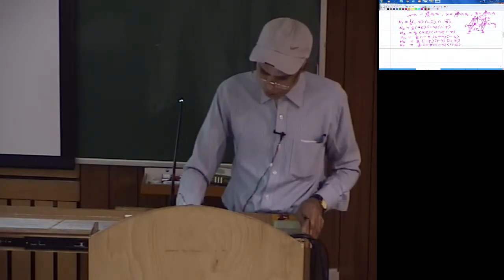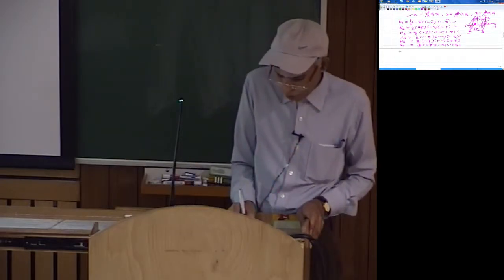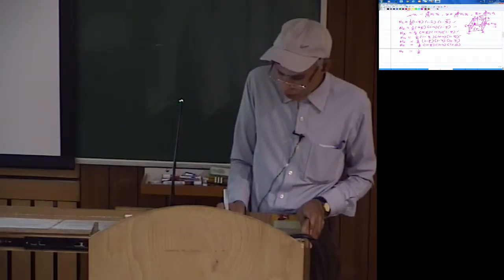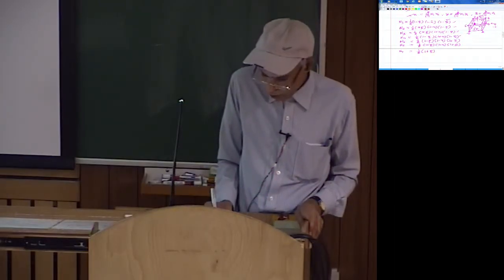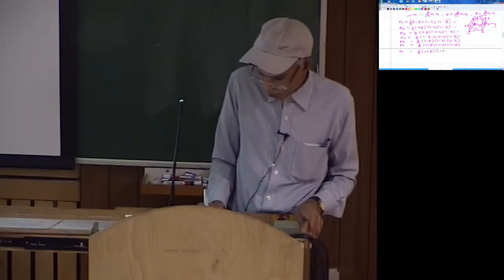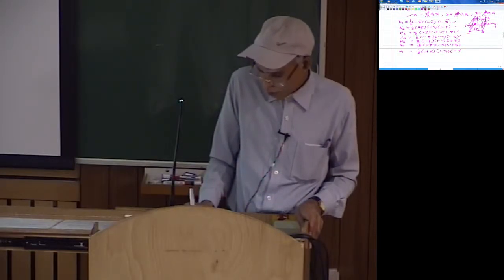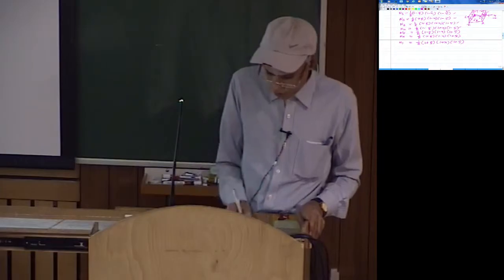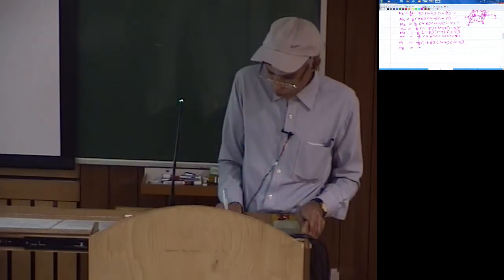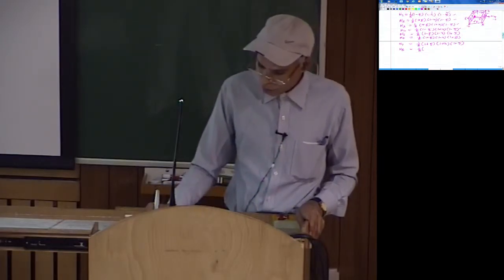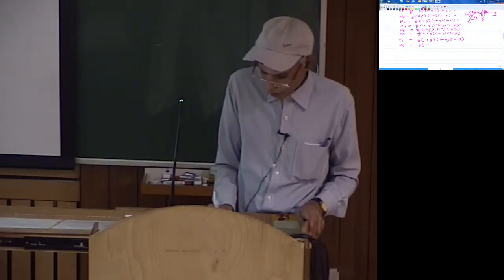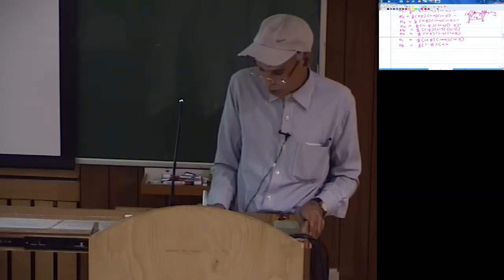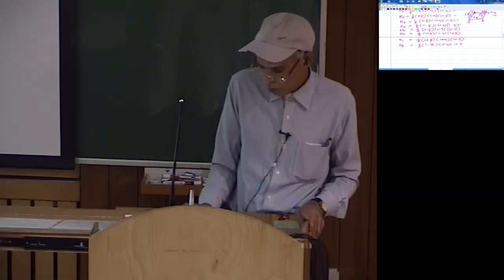So in all these you find the bottom 1, 2, 3, 4, this term is negative, here it is going to be positive. So N7 is 1 by 8, when you go to node number 7, you are shifting in the eta direction. So 1 plus xi, 1 plus eta and 1 plus zeta. And so also finally N8 is 1 by 8, and then from 7 to 8 you are shifting in the zeta direction, which is 1 minus xi, 1 plus eta and 1 plus zeta.